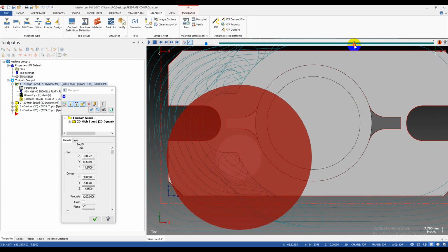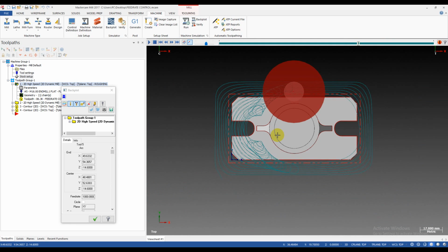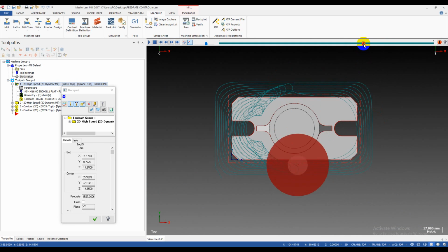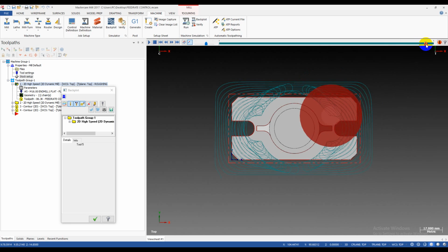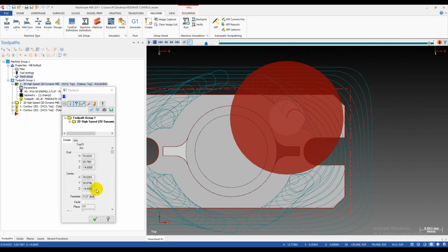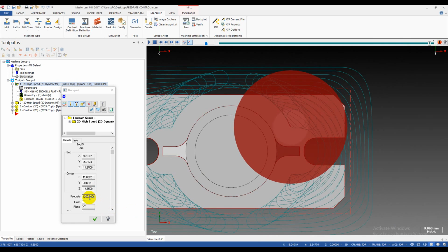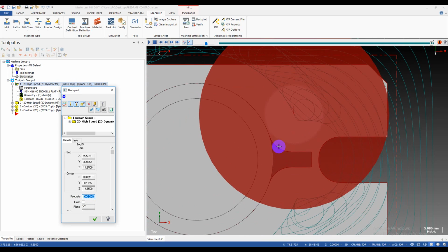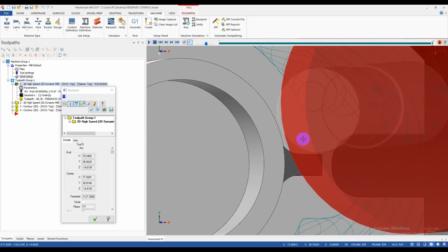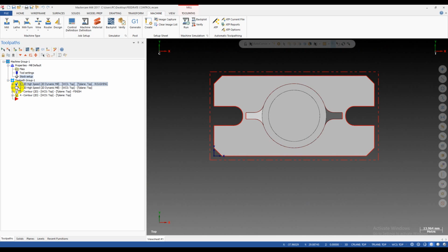If you want to reduce more, you can input a smaller minimum value. For example here, we have the minimum feed rate 1000 here, when the tool goes to the sharp corner, the small corner here. Okay, that's how the Highfeed function works.